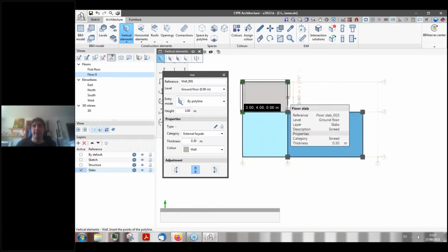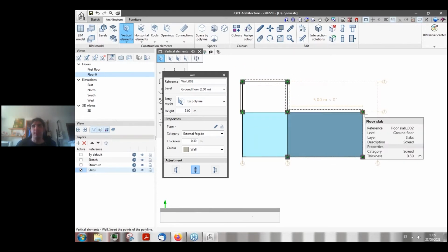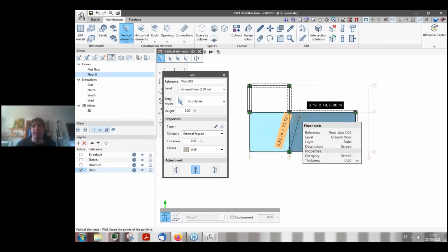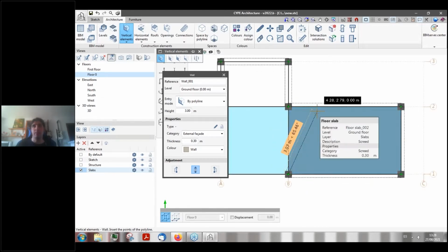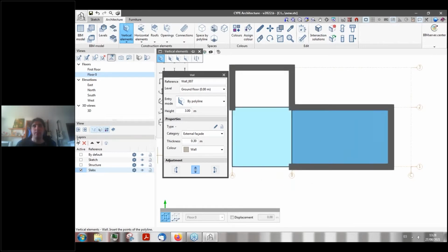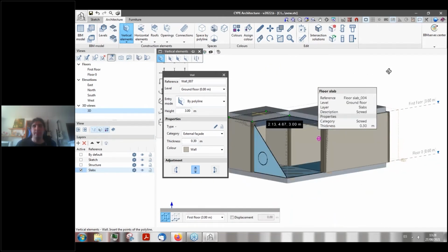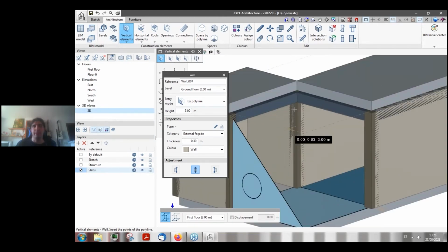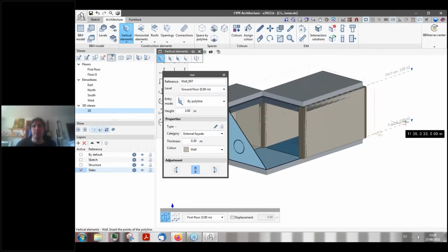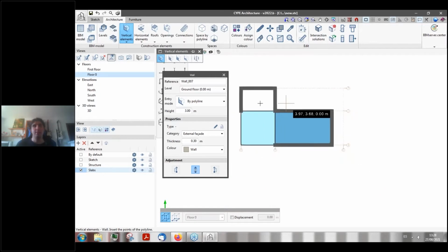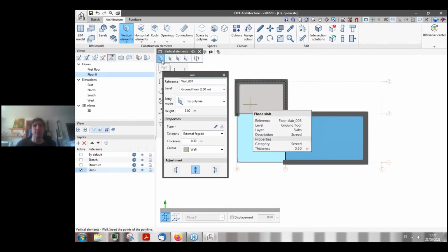As you can see here, I can insert all the different elements continuously, as if it were a polyline in AutoCAD, for example. Now, if we switch to the 3D view, you will see that indeed I have added these walls right here, and they are 3 meters high, and they are based on floor 0 because we'll be working with this floor view. Let's continue with the definition of vertical elements.